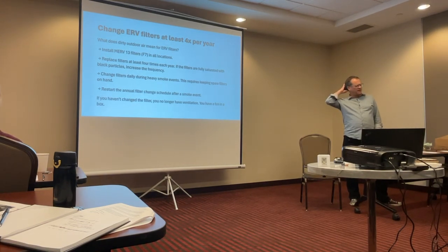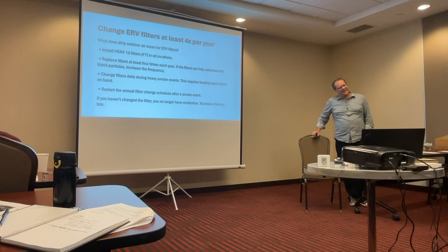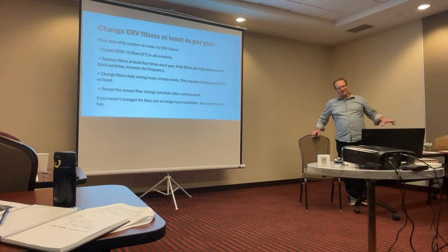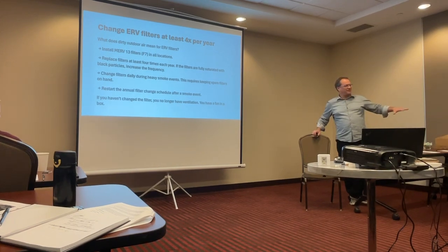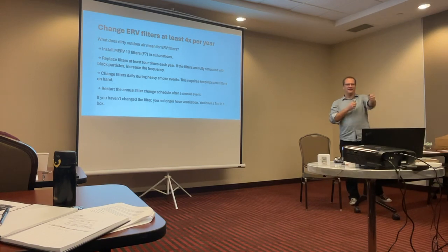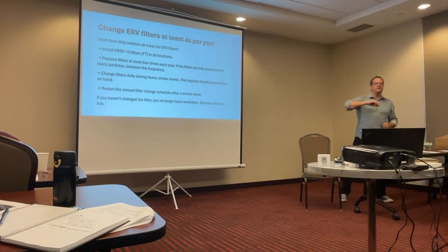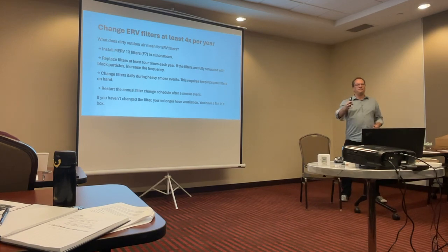We were talking about at least one building, when you take them out, if they can be vacuumed and set aside as B filters, you keep a giant box of slightly used filters for the smoke event. You pull it out and use those again, maybe vacuum again and reuse them, get by through the smoke event, and then as soon as the smoke event's over, install a brand new filter and restart your clock, whatever your clock is.